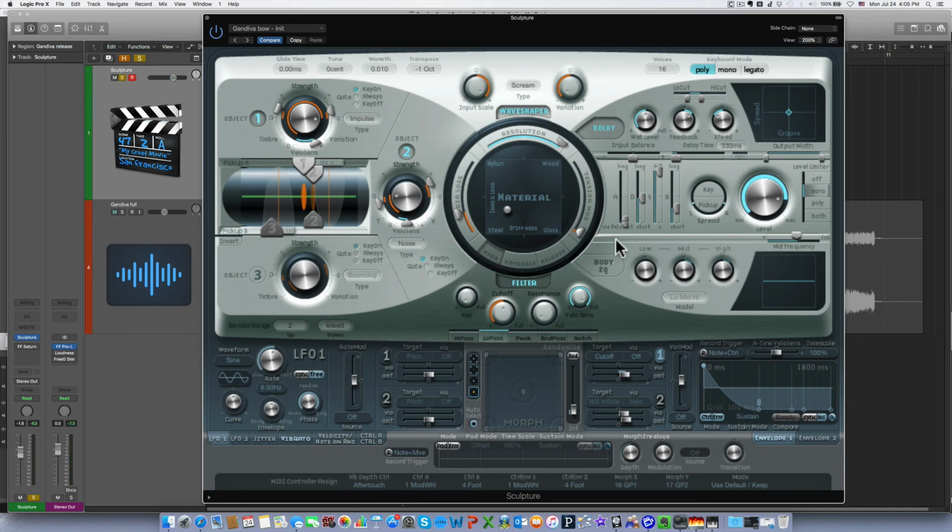From this section, the signal is going to go into an equalizer. We have a body EQ, which is supposed to emulate the sound of the box, if you will, or the enclosure or the space that the string is reverberating in. It is sort of a coarse level equalization. I picked a simple low, mid, high EQ and set the mids and the highs to bring them back out a little bit since we lost some of them during the filter.